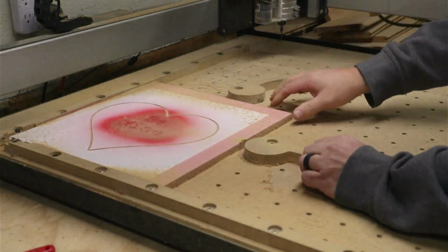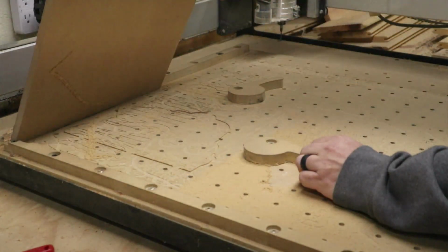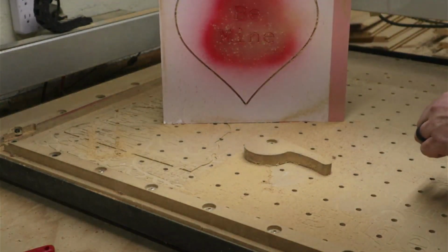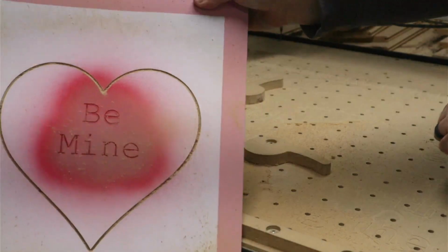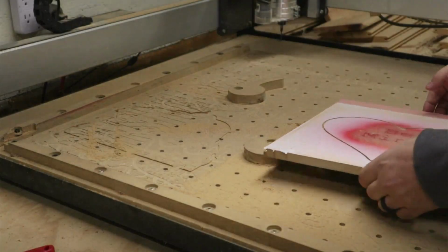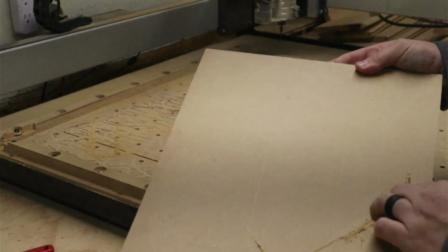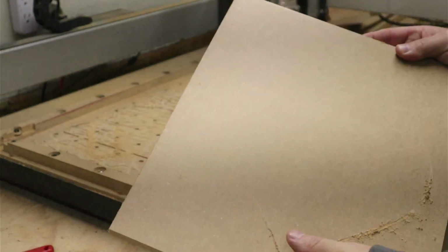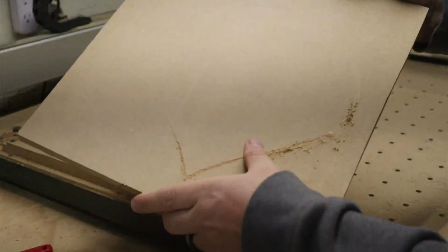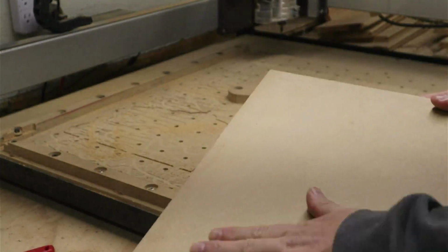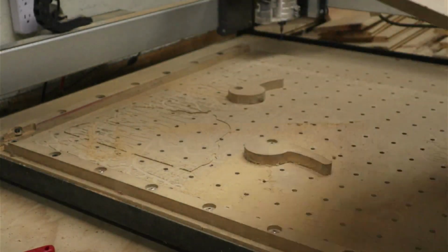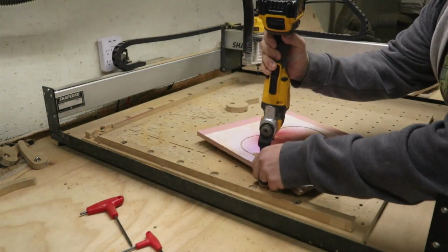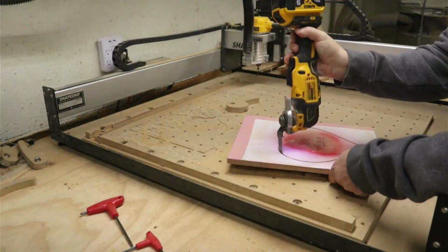Once the cutting's done, we just remove those clamps. We'll take it out of the machine, and you can see here that once I get the dust off, it looks pretty good. Everything's centered. Now as I flip it over, you'll see it went through on some parts and not others, and this is what I was trying to avoid. And like I said, you really want to make sure you have that bit set, the Z-axis set down as far as it needs to be. So my solution to this is to just cut with a reciprocating tool, just kind of finish it off.